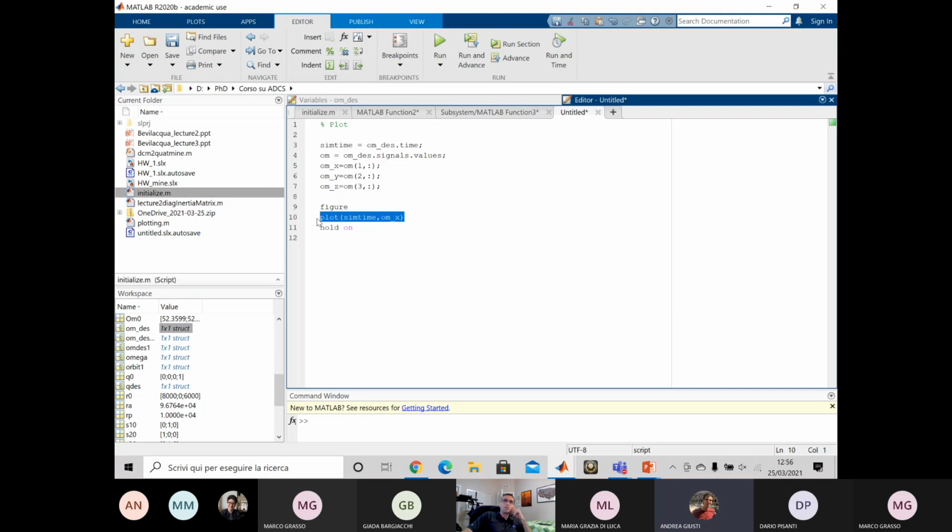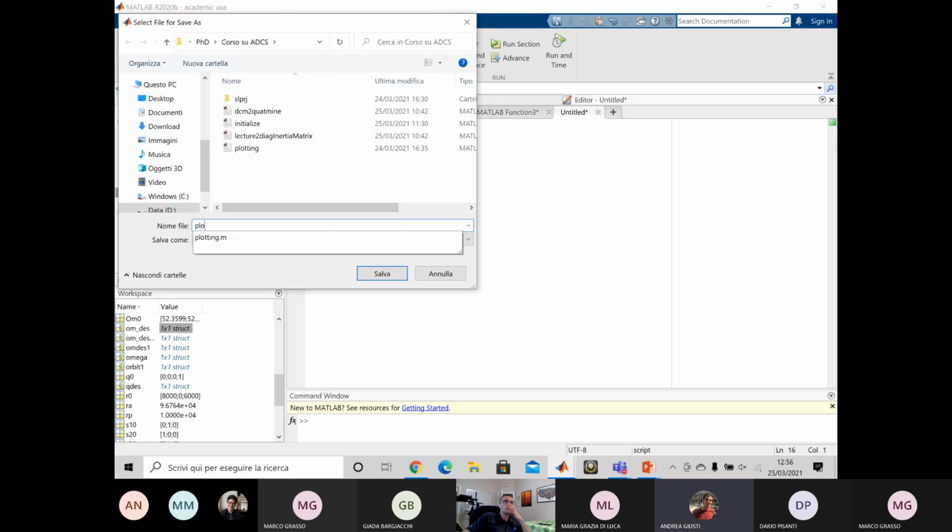But the reality is that the dynamics of the system, spacecraft plus actuators, for example the inertia matrix of the entire system, is not just J anymore. It's J plus the contributions of all those systems, the variable speed control moment gyros with the rotation matrices involved. So I'll do the derivation of the equations, and I think it's preferable to have a new block.